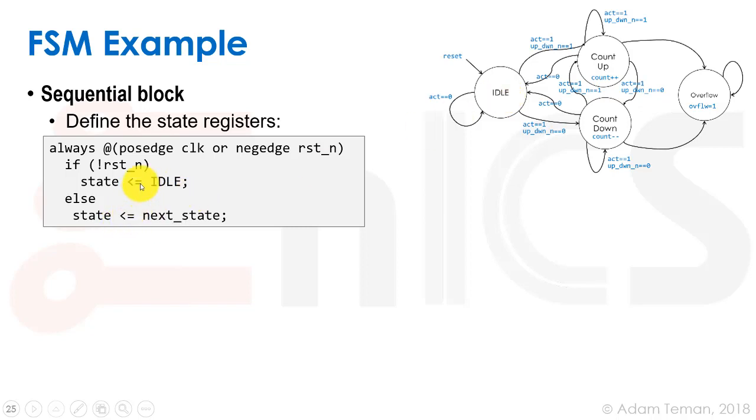And you see this is a non-blocking assignment because it's in a sequential block. So every time the clock goes high, state goes to next state. We traverse between these states. It actually made a bus of flip-flops, the state flip-flops. There is a bus of signals coming in called next state, and when the clock rises, next state turns into state. And this goes back into our combinational logic that figures out what the next state is. And that is how we made our state machine.